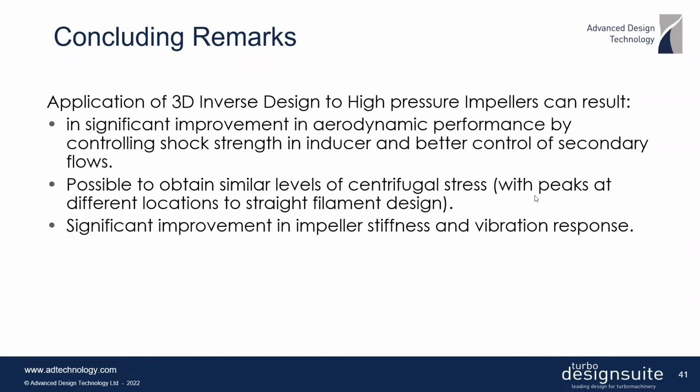In terms of stresses, for example, we saw in the Cummins case, we seem to have optimum performance with the straight filament design. And the only way you can actually get significant improvements is by looking at 3D impeller designs. And what we see, in fact, is that there are no significant penalties in terms of centrifugal stress for the 3D design compared to the straight filament design, as long as the 3D design is done carefully to minimize the lean angles at the leading edge. And also, we get significant improvement in impeller stiffness and vibration response, which is, of course, an added benefit.